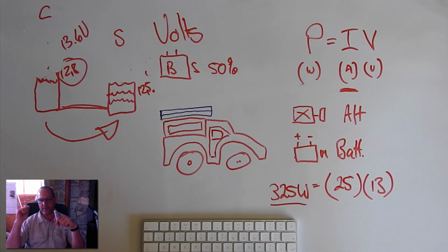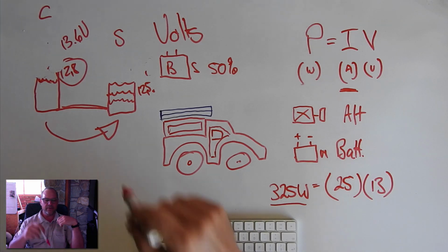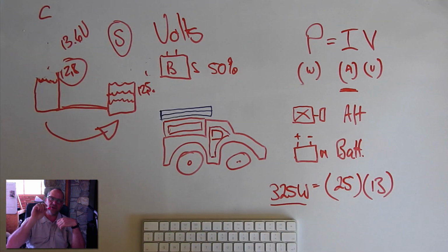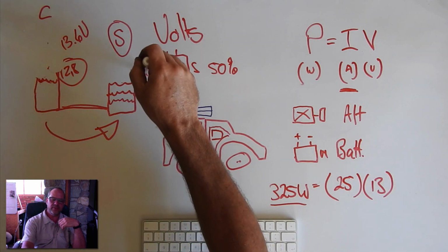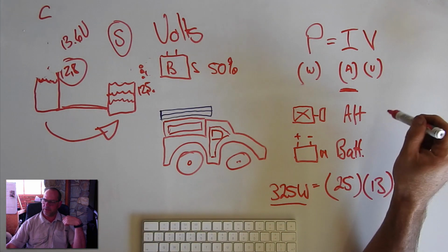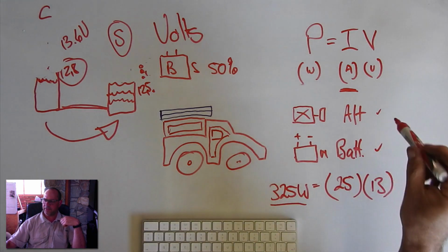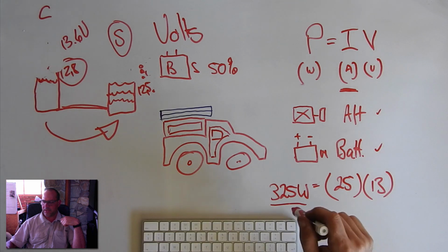If you start your vehicle in the morning, and this is something that I see quite regularly, or in the evening, let's say you've been standing at a campsite for a few days and you recognize that your secondary battery is running down, and you're sitting with just 3 red lights at the bottom. You say, oh, I have to do something about this. Let's run the car for half an hour. So if you run the car for half an hour, you are engaging the alternator, but you are also engaging your car's main battery. Now the alternator in that half an hour will only give you